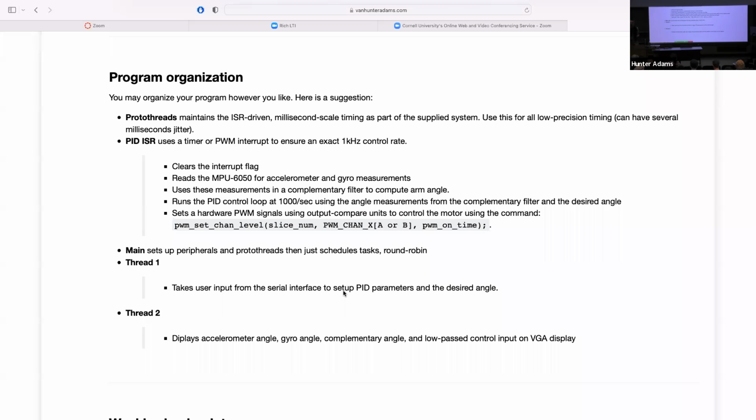So that if for your final project, you wanted to tie an interrupt service routine to one of the other available interrupts, there's something of a model here for how you would set that up. Right? So for instance, maybe you wanted to attach an interrupt service routine to one of the low-level interrupts associated with a DMA channel. This is an approximate model for how you would do that for a different interrupt service routine. So that was my motivation for setting this up using the PWM interrupt as opposed to a repeating timer callback function.